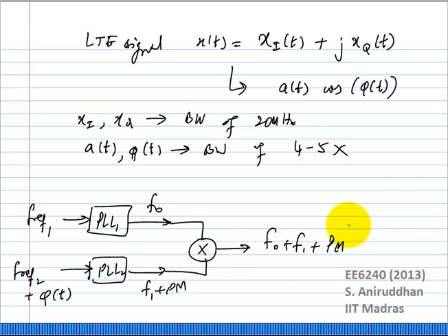There are really many different ways of doing this phase modulation using PLLs. Now in this what you are doing is, instead of using the same PLL, you are actually using a different, maybe a low frequency PLL to make the phase modulated portion easier, and then you are mixing it with the high frequency PLL to actually add the two. Now obviously you need to look at the non-idealities of the mixer itself. Mixer will produce spurs and so on, phase noise, spurs, everything. But people have done these kinds of topologies before, these kind of architectures before for these kinds of transmitters.